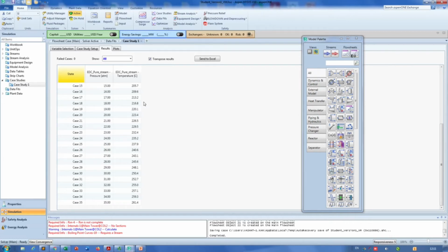Okay, Aspen HYSYS is a software, but still, 35 to 50. Okay, this looks okay to me. So this is your bubble point temperature as a function of pressure, because we already said vapor phase is equal to 0, which means our stream is at bubble point.